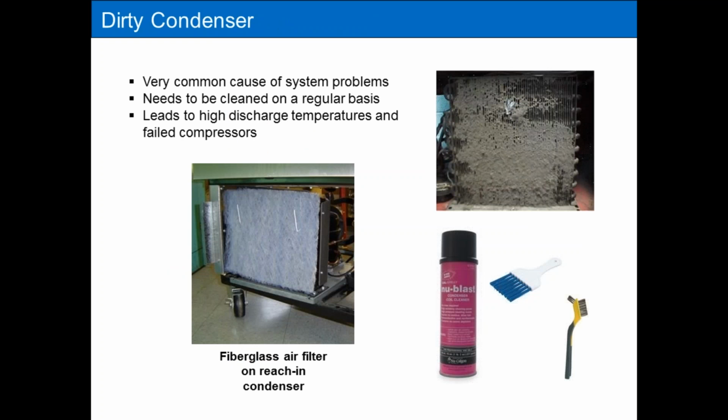So let's talk about one of the most common reasons for failures: dirty condensers. Pretty routine. And you would think in a kitchen, in a food service environment, that it would take a lot for condensers to get dirty because it's a clean environment, but that's not true at all. They get pretty plugged up pretty bad. And how you clean them, or the method of cleaning these, does need some consideration.